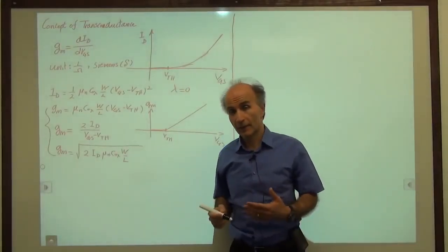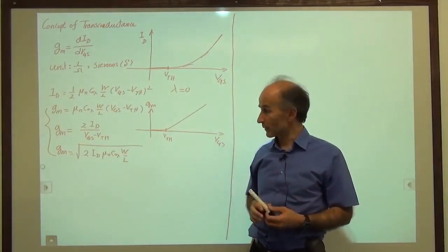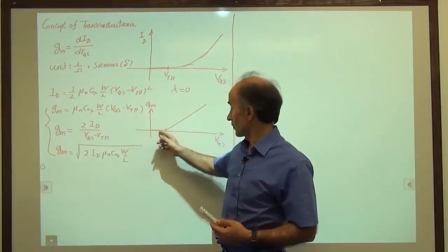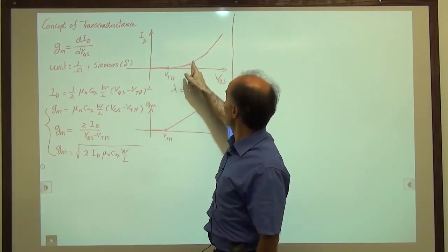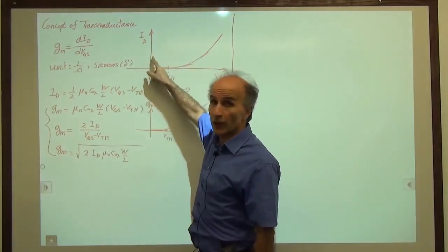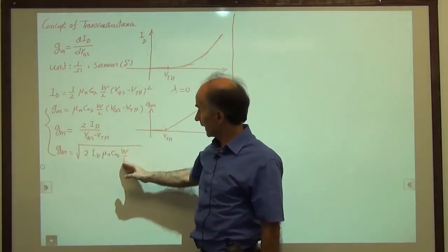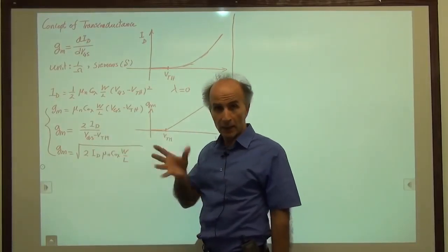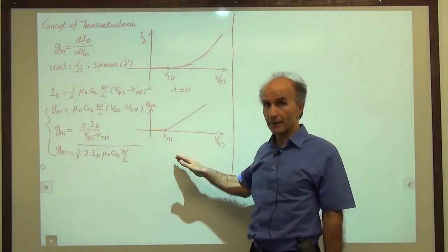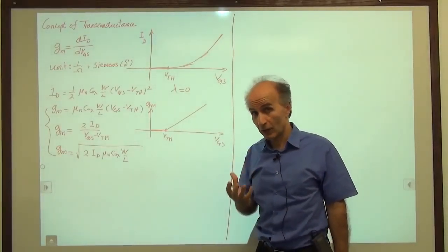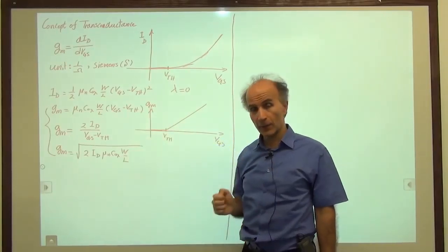And it's very interesting because each of these equations tells us something about how GM varies with various parameters. GM varies with VGS minus VTH, yes. GM varies with ID, yeah, we saw that, right? We saw if we have biasing here, we have a lower GM than if we are biasing here. And then GM also varies with W over L, as indicated here and here, and also some interesting things. So these are things that we have to study in the future. But the transconductance of a MOS device, which tells us how strong the device is in converting a voltage to a current, has these three expressions for it.